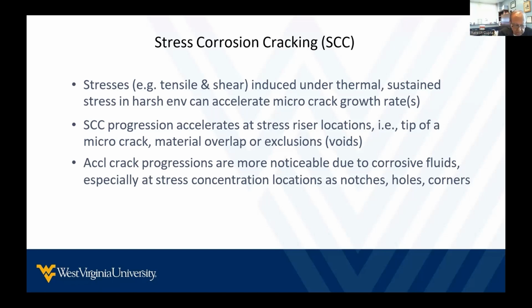It softens or plasticizes the matrix. It makes it soft, and therefore, at places where there's stress concentration, you can have creases, which then lead to cracks. And obviously, this is accelerated by an increase in temperature.